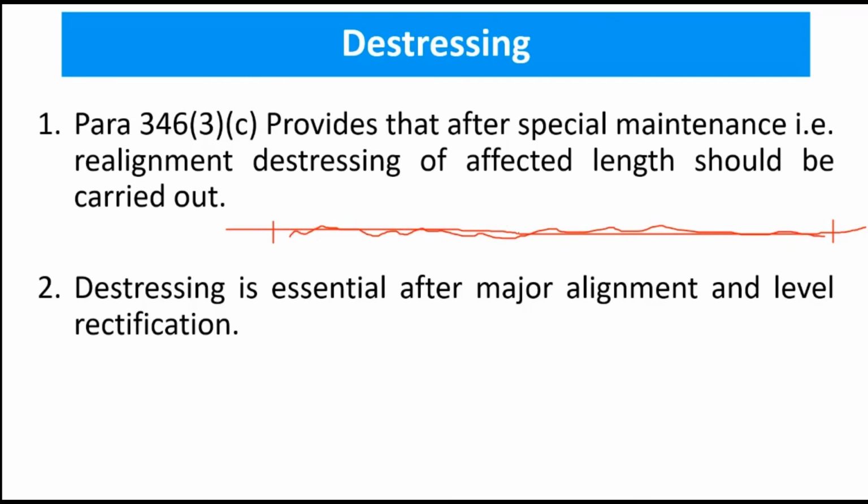So due to this, stresses get locked up in the rail. By doing the de-stressing, we remove these locked up stresses, so that there are no chances of buckling or similar problems.